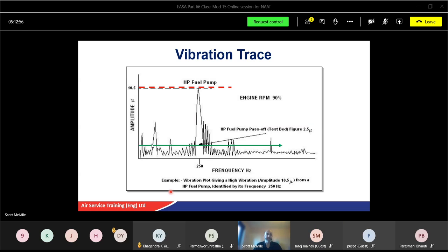Something's annotated as delta P. Americans brought this into line. So a little triangle beside P, T, or whatever means the pressure differential or temperature differential. Anything with delta means changing. And with the fuel pressure one, if you've got a pressure differential switch, it gives the warning that the filter is about to become blocked.